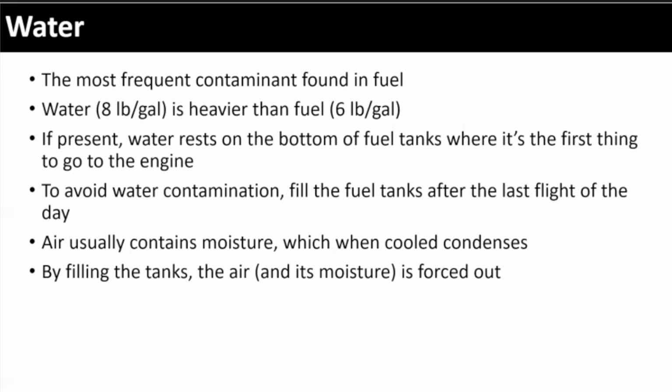Condensation, right? So when you don't have full fuel tanks, what's taking up the volume in that tank that's not being taken up by fuel? Air. What tends to happen to air when it gets hotter and colder? You get condensation. Condensation in the fuel tank becomes bad.